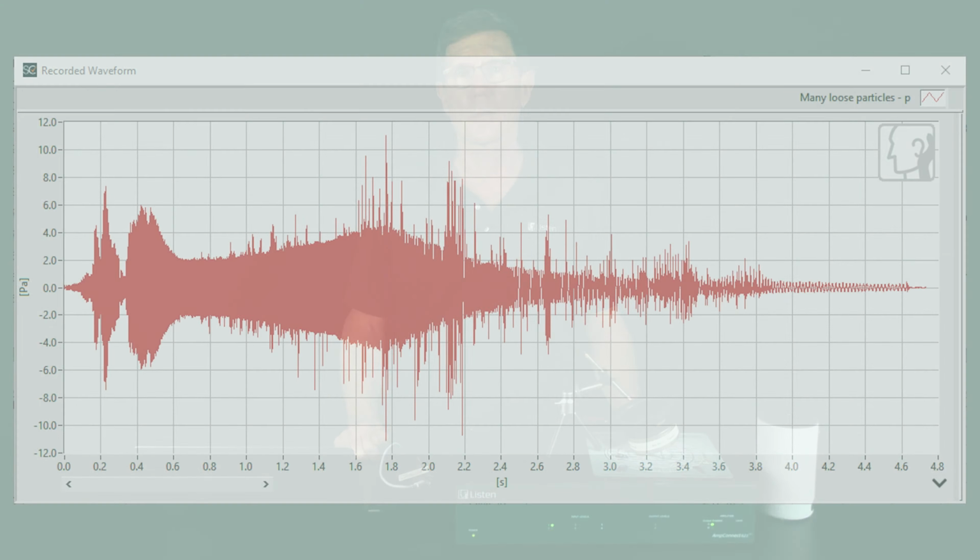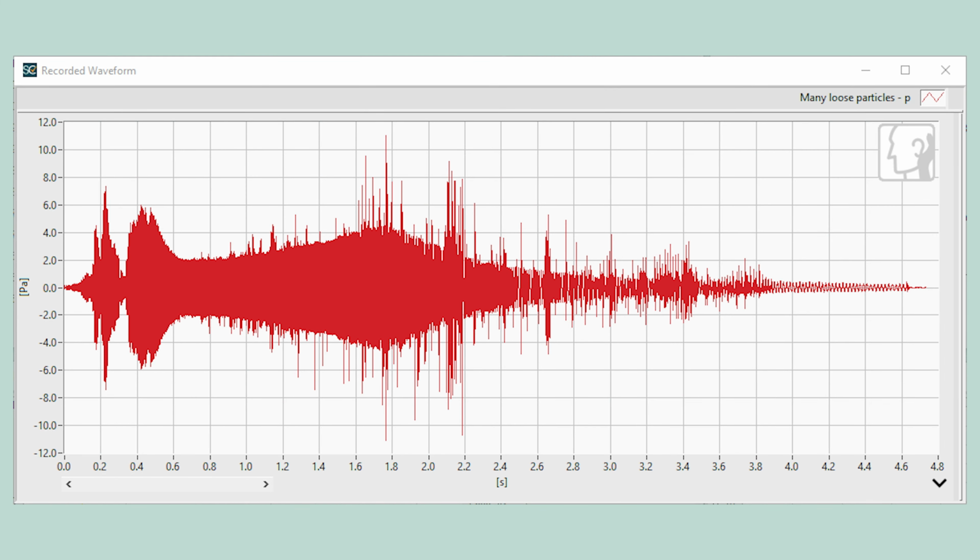Now let's look at the waveforms for the bad speaker. You can see the transient distortion faults appear as impulsive noise on top of the stimulus wave. These impulses are not related to the frequency of the stimulus, but rather to the vibration caused by the displacement amplitude of the diaphragm. The transient distortion is more frequent and significant when the speaker is driven near or below its resonant frequency, where the displacement of the diaphragm is greatest.